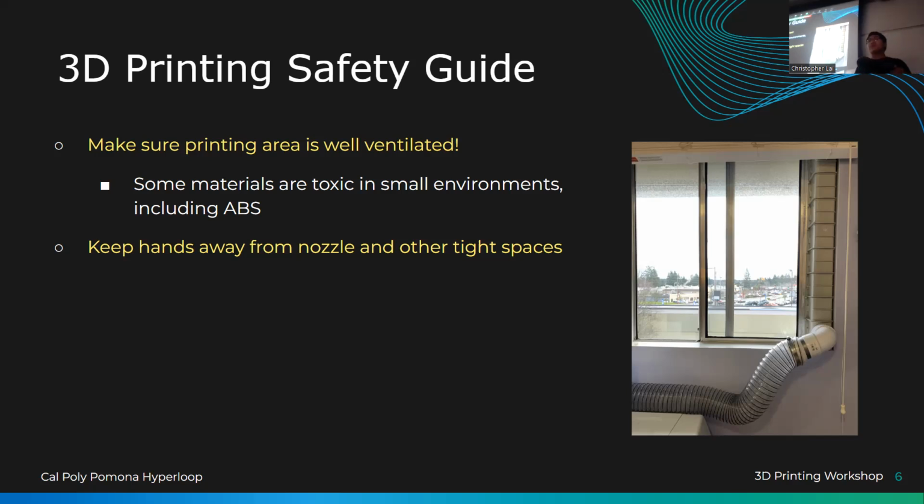So when you are installing or removing a nozzle, make sure the hot end is preheated to some high value like that. And you're going to probably ask me, if I want to keep my hot end hot while installing a nozzle, like you just told me to keep your hands away from the nozzle, so aren't my hands going to be relatively close?